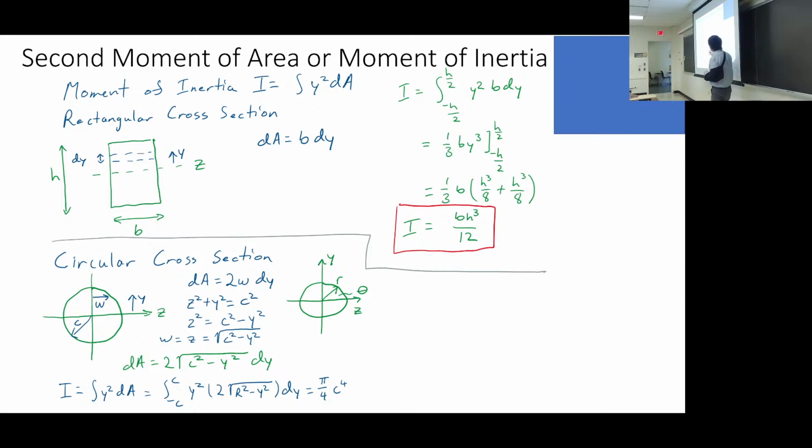So now I've got bending moment, which for many intents and purposes is P times L. And I've got a thickness in the numerator, y, plus or minus y, and a thickness cubed in the denominator. So the bending stress goes with 1 over h squared. Does that ring a bell?